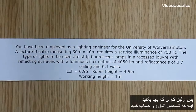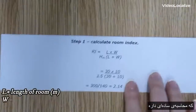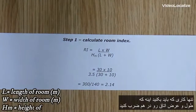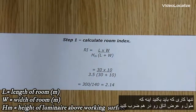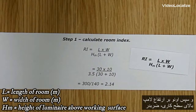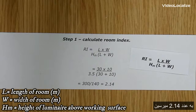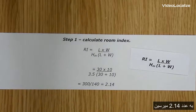So first thing you need to do is calculate a room index, which is just a simple calculation. All you have to do is the length times width of the room and then divide that by the height of luminaire above working surface times the length of the room plus the width of the room. So after you've done with your calculation, you'll get a number of 2.14.